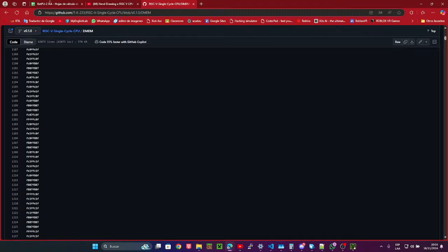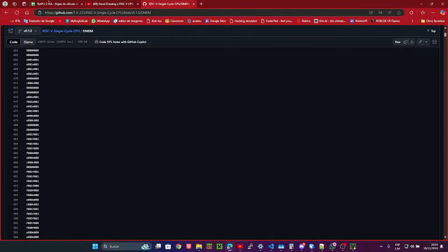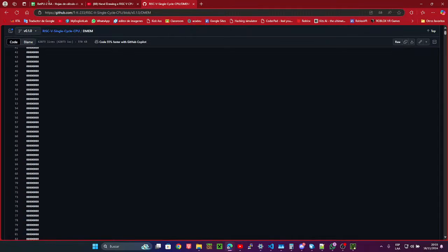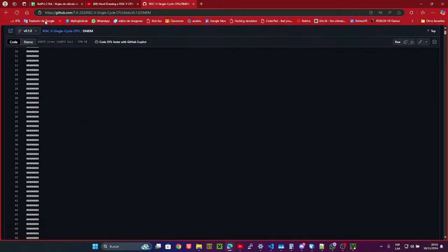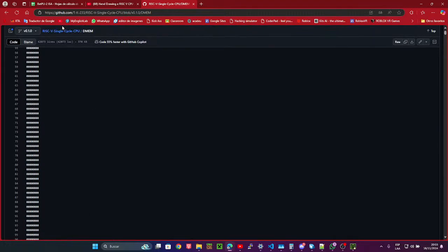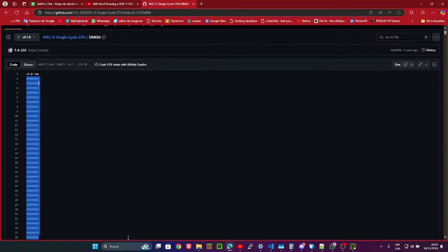And turns out it's 640 horizontal pixels. They give you some more delay at the end of the line. It ends up being about exactly 800 pixels worth of time for each line, and the whole screen is 525 lines worth of time.